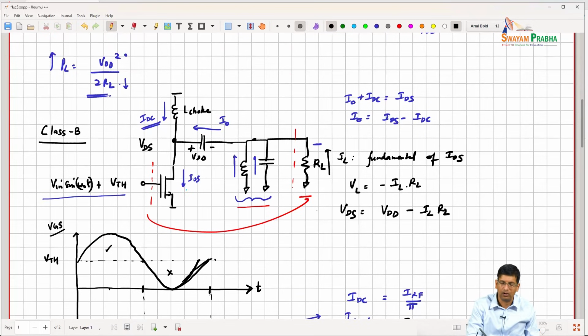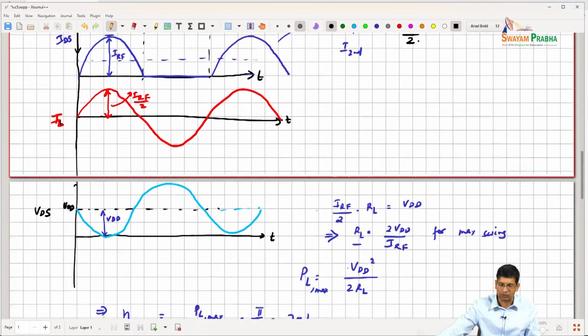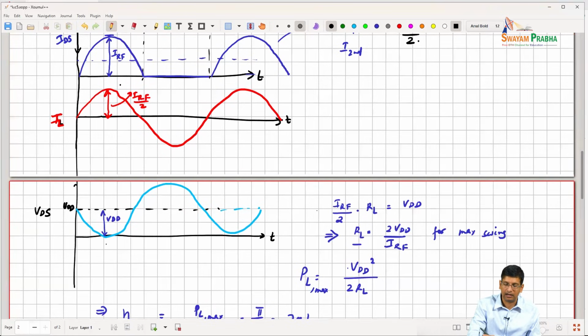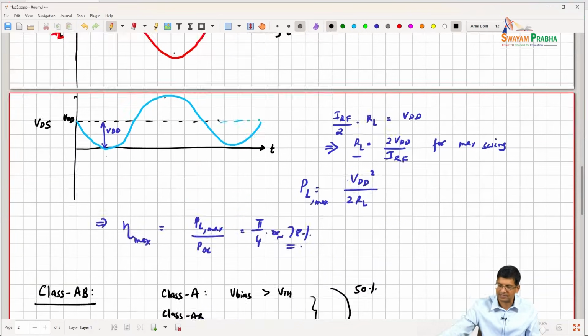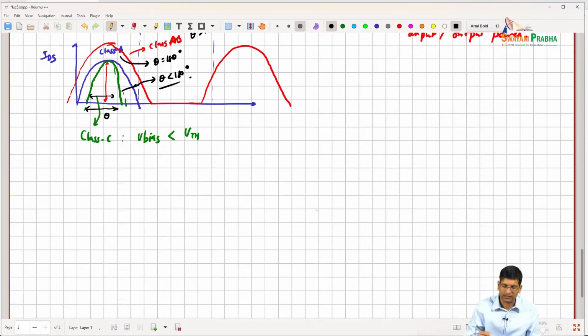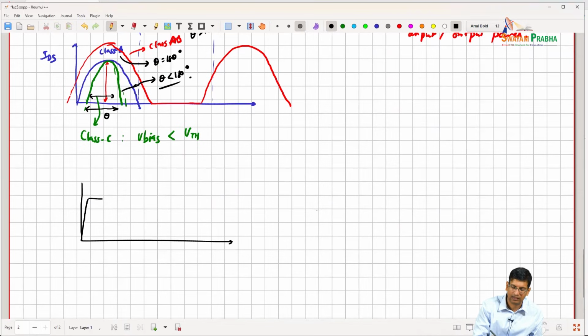You're trying to, from a system level, create an objective, because what we see over here is that the I peaks when the VDS goes low and the I goes low when the VDS goes high. So if I think about it as power dissipated in the transistor, this is a good scenario, but the best case scenario for me would be a situation where I could make a plot where the IDS looked like this.